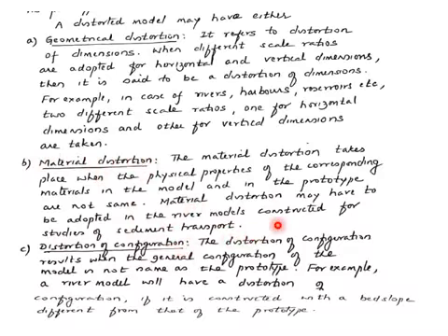Sometimes the bed slope in the river is different from the bed slope in the model, to get enough slope and velocity so that we can predict the results properly. That is why distortion of configuration takes place, for example in a river model that has to be constructed with a bed slope different from that of the prototype. So such distortions are either geometrical distortions, material distortions, or distortion of configuration. Such models are known as distorted models.